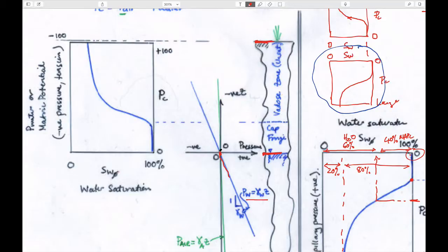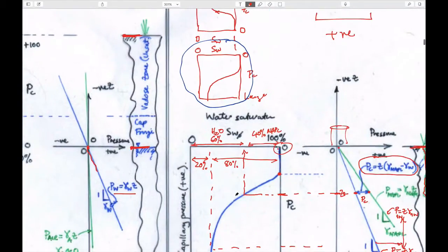And if we went above the water table, where we're holding the water up by its bootstraps, if you think about it, then it goes at exactly the same slope. It happens to be compressive pressure below the water table. It's in tension above it, because we're physically picking it up in a capillary by interfacial tension. And so this blue line is continuous as we go across here. That is no different from what we had before. We just didn't draw it as it went across here.